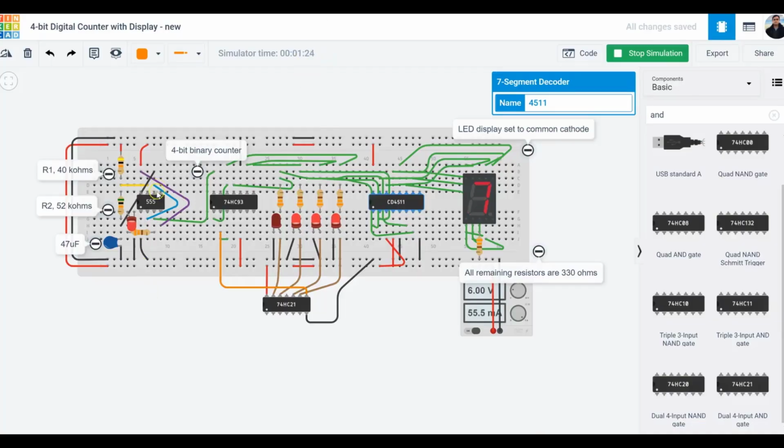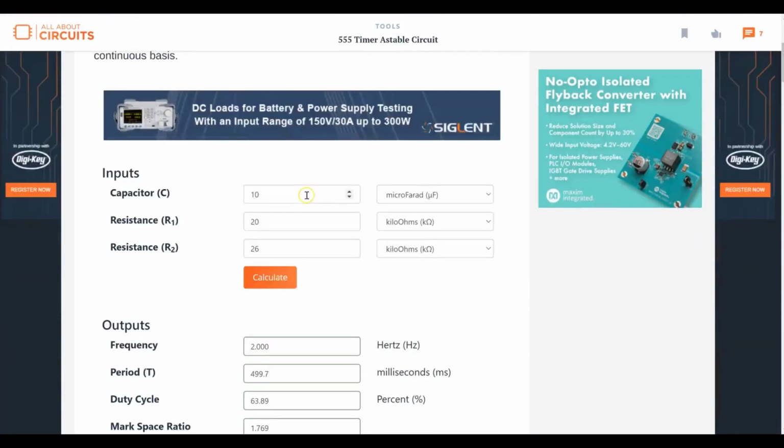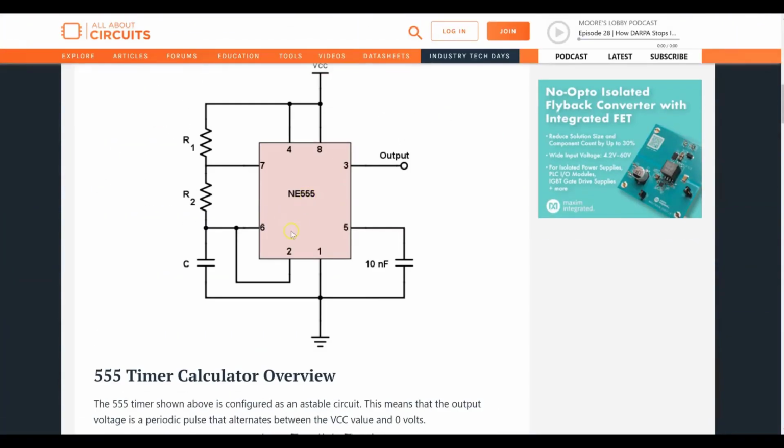over here, and I'm gonna explain this circuit right here. So 555 timer, this is the ground simply connected over here. Okay, you have pin number 2, which is basically shorted with pin number 6 over here. If you go back here and if you look at the circuit, pin number 2 is just shorted with pin number 6, correct? Okay, let's look at pin number 3.